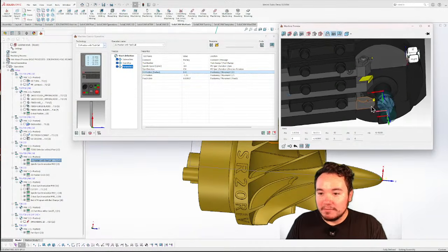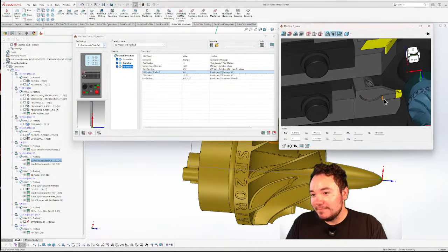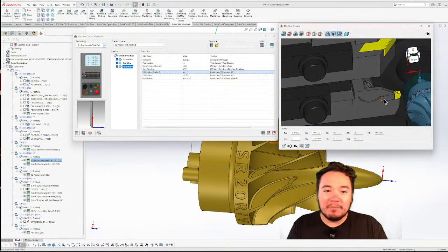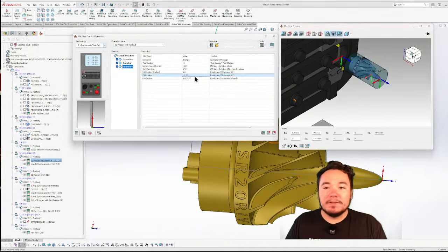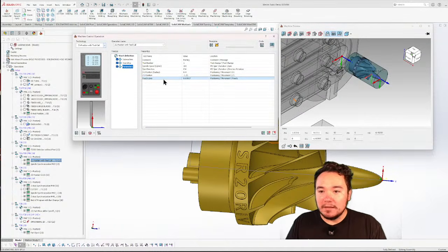Now X1 radius call out. So where is the X going to stop before the cutoff? So you have that starting right there. And then Z1 position, the stick out of how far you want Z to come out, and then feed in for the positioning.